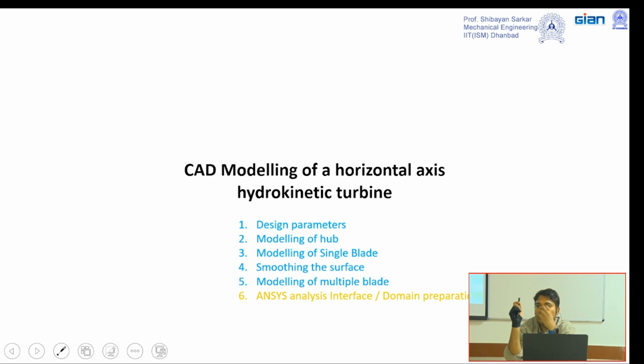Then torque problems will also arise in this particular area because of this non-uniform sort of blade. Again, whenever fluid passes over a particular channel, the fluid which is interacting with the solid surface, that means the river bed, will have a lesser velocity, and the fluid passing through the almost free surface area will have a higher velocity. So that is also creating problems.